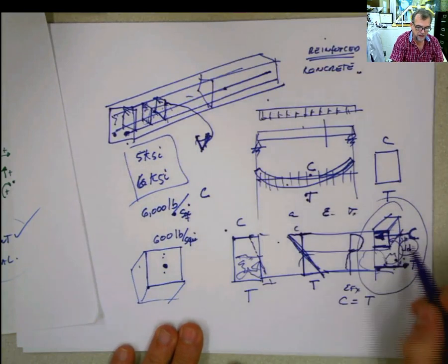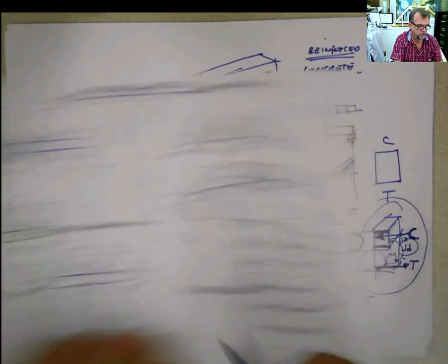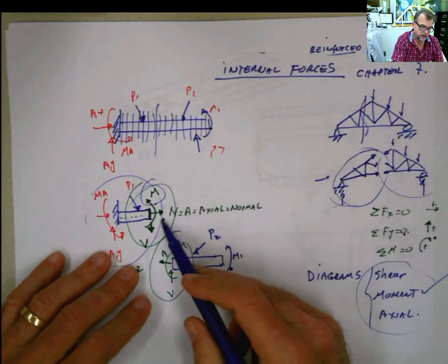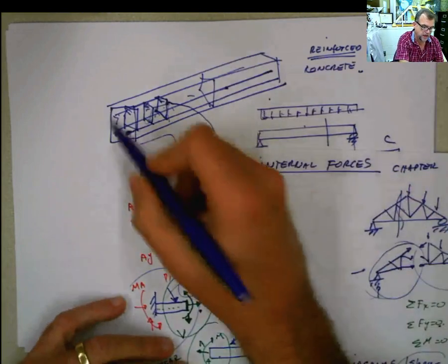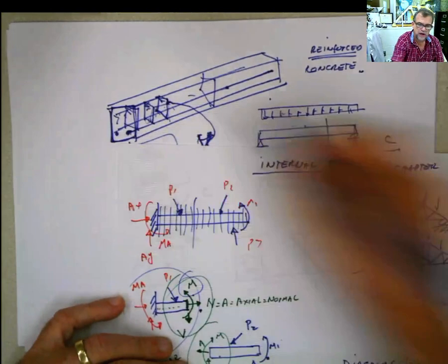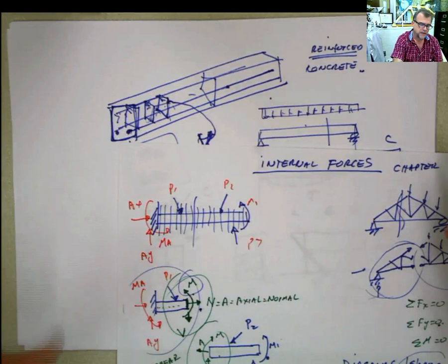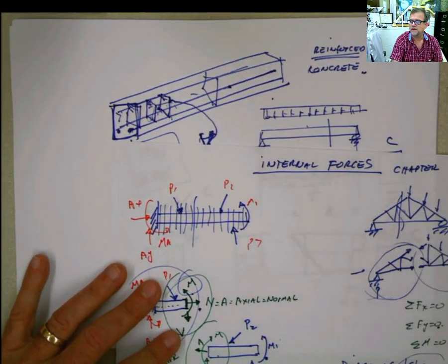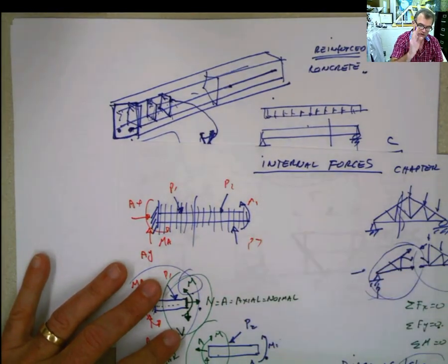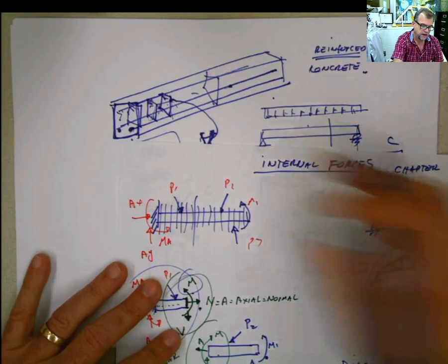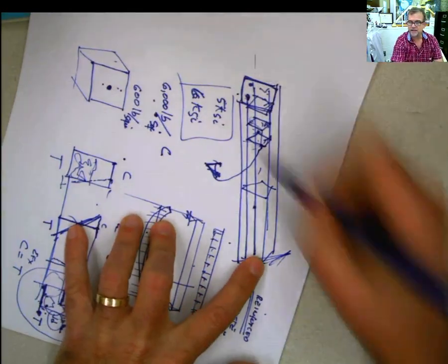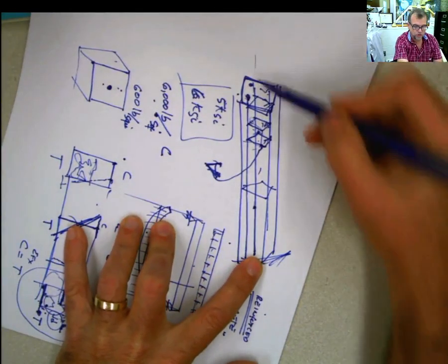And finally, you have the axial force. What do I use the axial force for? Well, you use the axial force for several things. One of the things is for designing the cross-sectional area also. And do I have axial forces in beams? Yes, you do have axial forces in beams. Of course, predominantly you have vertical, or rather transverse, forces and moments. But now this is a beam, perfectly. Now if you consider this like that, now it's a column. And yes, you do have axial forces.